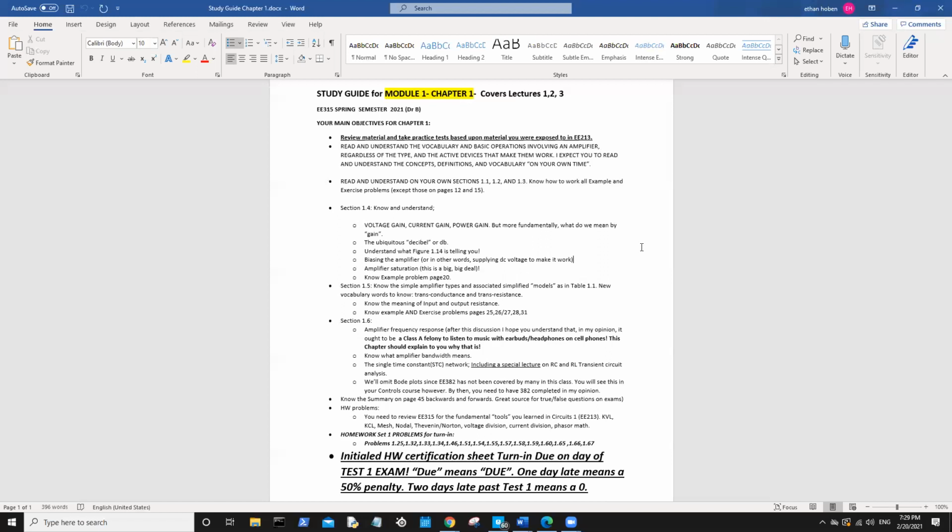All right. Then I guess something we haven't talked about at all because it wasn't on the test was the cascaded amplifiers. Although functionally, if you understand what the word cascade means, it's pretty easy. Basically, just know that term. It's the expanded gain, where it's V out over Vi times Vi over Vs. You're just expanding that for the number of stages that you have. Then we have section 1.6, amplifier frequency response.